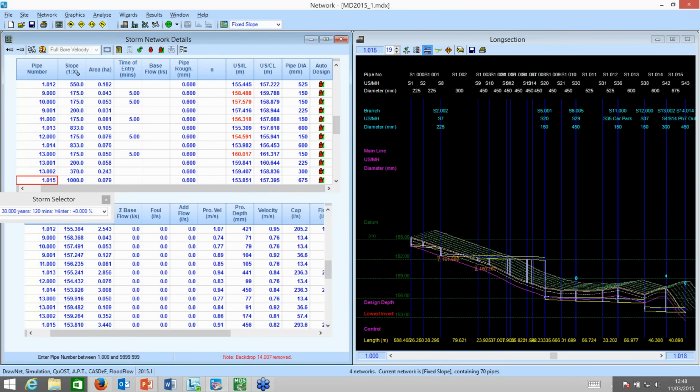And you can see that on the left-hand side now, all of those pipes have now got the slopes that have been specified in that pipe size file. And it's also showing you the consequences. We've got a little branch line here that's going off under the topography there that's dragging everything down. But we have pipes coming out of the ground. Now, this doesn't surprise me because this is a relatively hilly site.